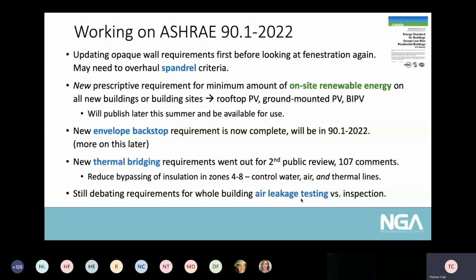And then probably the other big change is in places like Southern California. I'm not sure that everywhere there is using thermally broken frames and argon. They should be, but I've also heard they're not. This will force fabricators in that area to have that technology if they don't already, and hopefully have better frames using argon gas fill, bringing in warm edge spacers if they don't have them already.